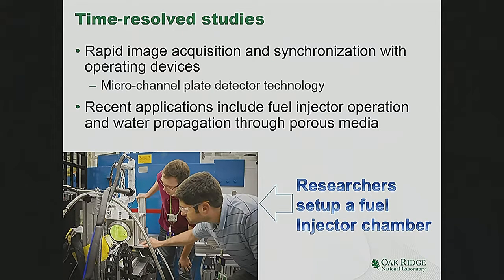We're firing that injector, and over time, by synchronizing several pulses, we could detect things like whether cavitation is occurring within the injector, for example. And since fuel injectors are such a mature technology, they're trying to optimize every last fraction of a percent of efficiency. So they want to know the details of what's going on inside the injector.